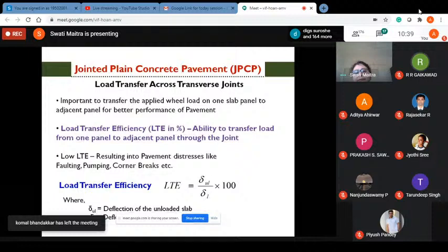So now the concrete pavement can be analyzed with loads due to wheel load coming on it, and with that we can find out where the critical location for stress on the pavement is, and how much the stress is. From this type of modeling, we can find the location of critical stress and the amount of critical stress, and from that estimate and further design our pavement.